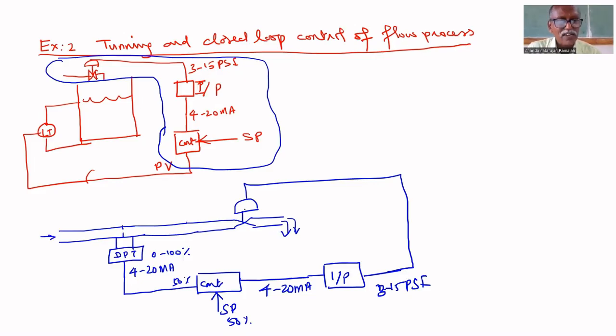The flow rate is adjusted by this valve opening. If you close the valve, it increases the resistance to flow rate. That's why flow rate decreases. But the pump here always pumps the same amount. Because of the resistance, the flow rate decreases.